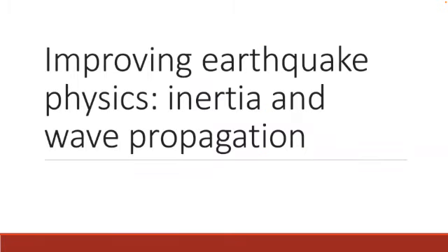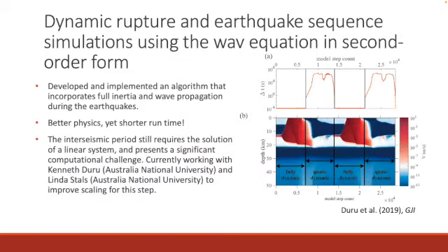Next, I'll talk about work that I did to include full inertia and wave propagation in my code. The previous results were performed with an approximation to inertia called the quasi-dynamic approximation during the earthquakes. Kenneth Duru, an applied mathematician at Australian National University, Eric Dunham, and I developed and implemented an algorithm that incorporates full inertia and wave propagation during the earthquakes. The new and improved algorithm produces more accurate earthquakes and is actually much faster.